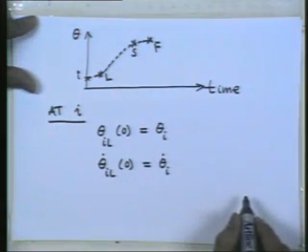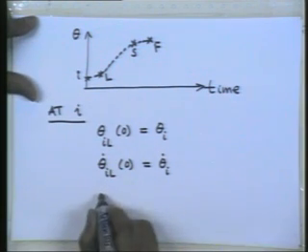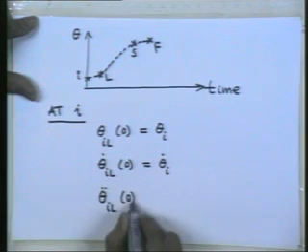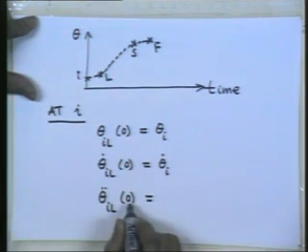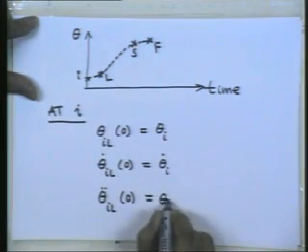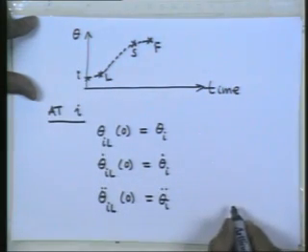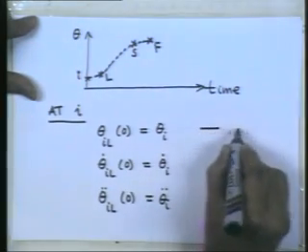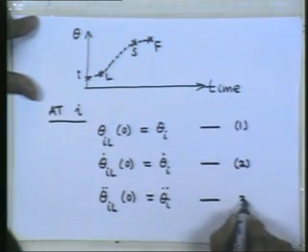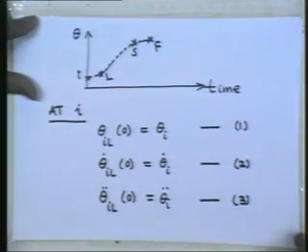These are prescribed position and velocity conditions. So similarly theta double dot IL, the 4th degree polynomial that you are fitting, at tau equal to 0 at the initial position I should be theta I double dot that has been prescribed. Okay. So we have, let us say, 1, 2, 3 conditions. Okay.